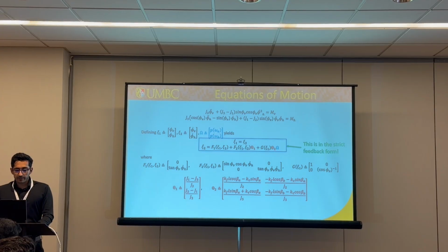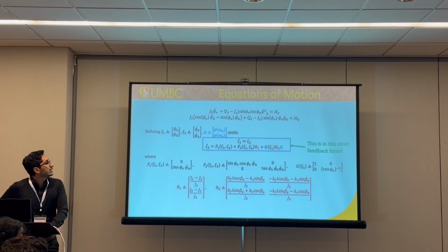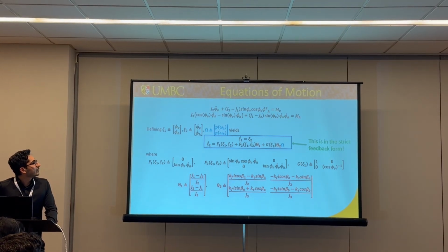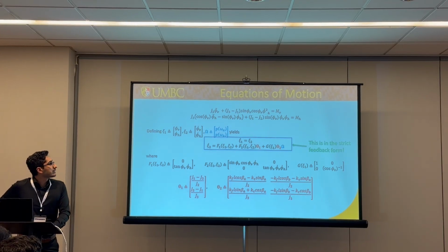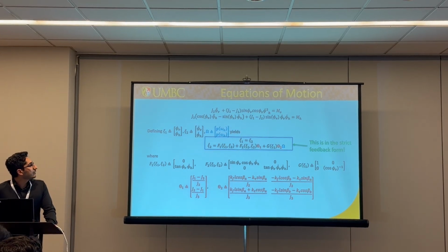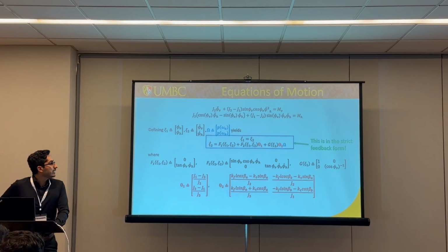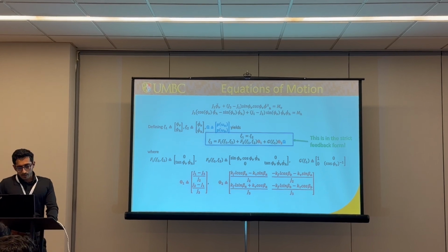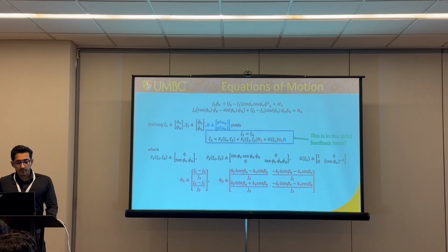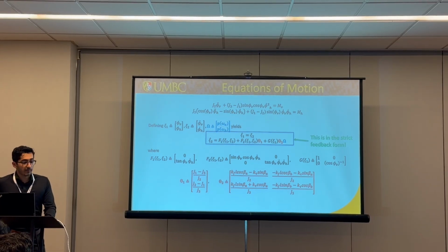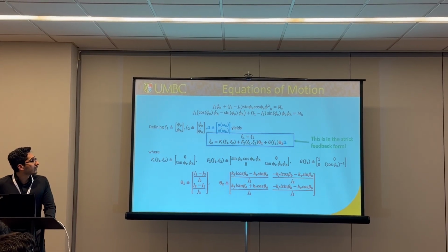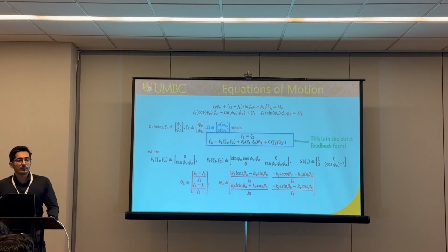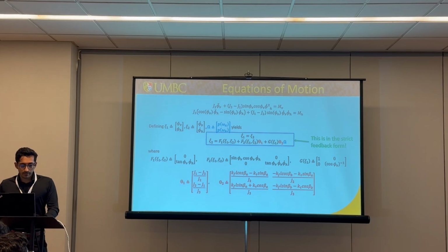The equations of motion of the system are derived with the Euler method. You can see them at the top. We are dealing with 2 differential equations of order 2. So we consider our state vectors to be the angles and the angular rates, and our input would be the speed of rotors. By considering these states, we can write our model in the strict feedback form as shown in the middle. The strict feedback form helps us to easily apply backstepping and IOL control techniques to our system.